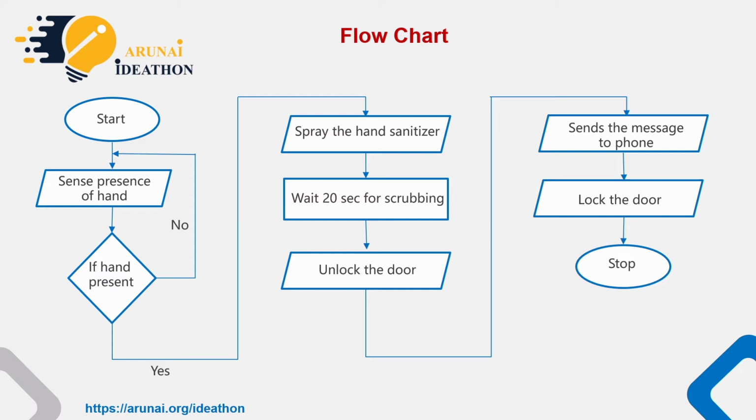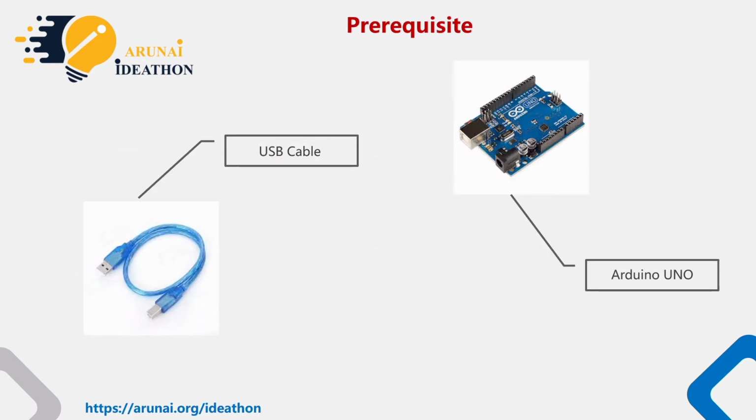Let's take a look at the components which were incorporated. So here comes an Arduino Uno. You may raise a question: why have we used Arduino Uno instead of any other microcontrollers, since other microcontrollers can also be used? The first and foremost thing, it comes with an open source hardware feature that permits users to develop their own kit, and it also uses Arduino code to match with the programming language libraries, and it is also simple to use for a beginner.